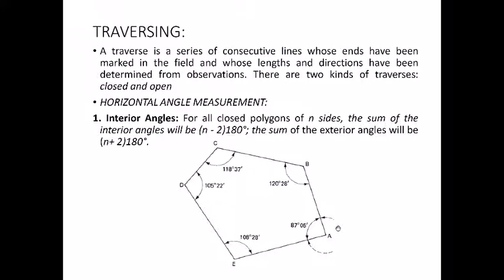ranging rod or leveling staff, I set my instrument equal to 0, and then I rotate my instrument so that I bisect the other point, and then the angle that my instrument would give me would be the interior angle E, or the angle AED. Now this measurement is similar to how you used to measure angles on a piece of paper using your protractor.